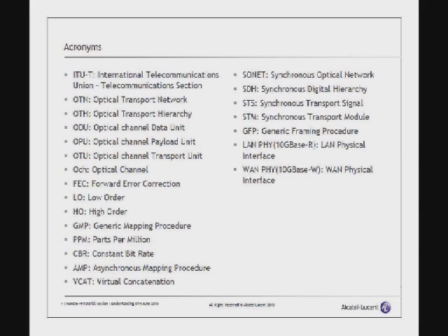The optical channel, which is truly the information that is put over the light down the fiber, is built up into these three components that make up the optical channel. Forward error correction is pretty key in the optics arena, being able to send information along that allows you to correct for problems and impairments on the line, and improve the bit rate that is transmitted and the quality of that bit rate.